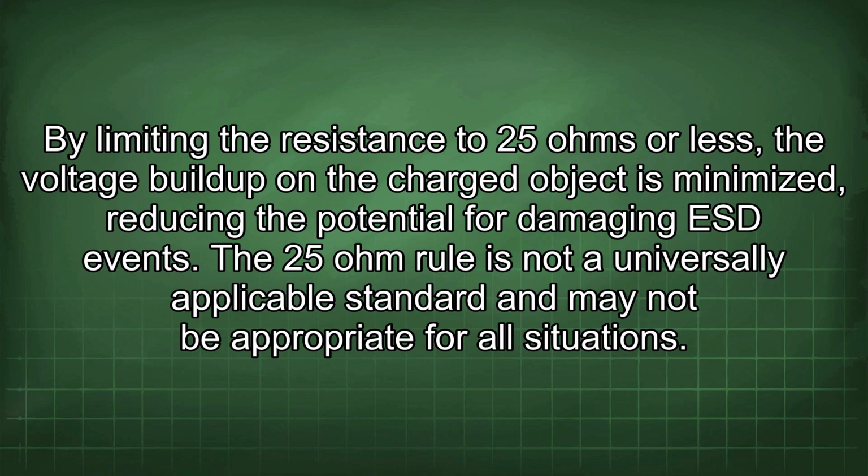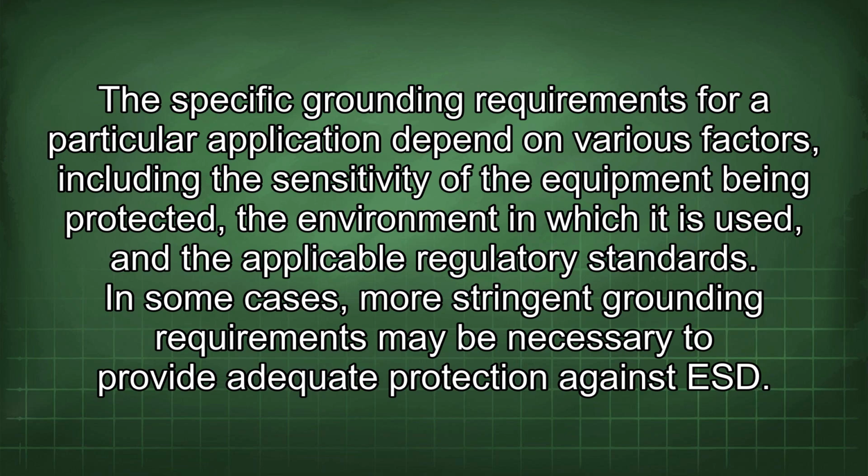The 25 ohm rule is not a universally applicable standard and may not be appropriate for all situations. The specific grounding requirements for a particular application depend on various factors, including the sensitivity of the equipment being protected, the environment in which it is used, and the applicable regulatory standards. In some cases, more stringent grounding requirements may be necessary to provide adequate protection against ESD.